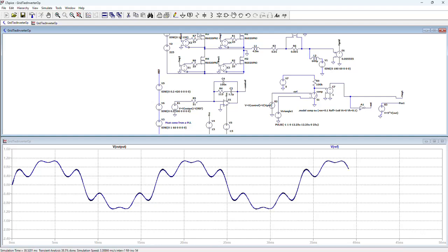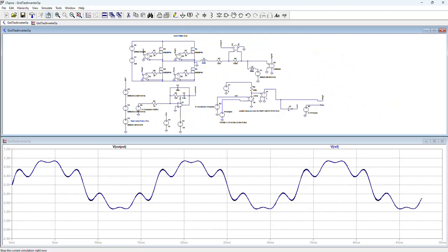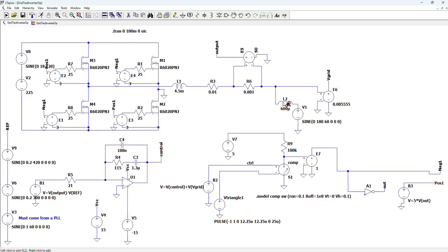As a conclusion, we can see that this controller is quite good to reject disturbances, to work under grid impedance. Of course, there are a lot of improvements that we can do here. For instance, modifying a little bit the controller to have passivity features and external stability and other stuff. But as a first moment, I can conclude that this controller is quite good. It can work as an active power injection, but it also can work as an active filter, because just having one controller with a large bandwidth we can see that this controller can inject harmonics without modifying the controller.